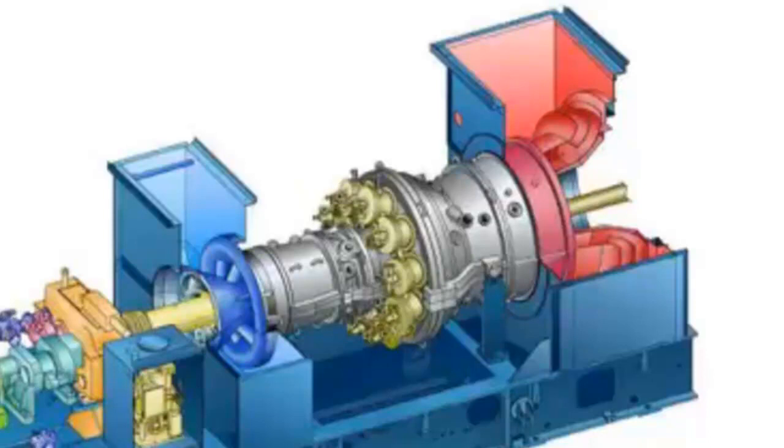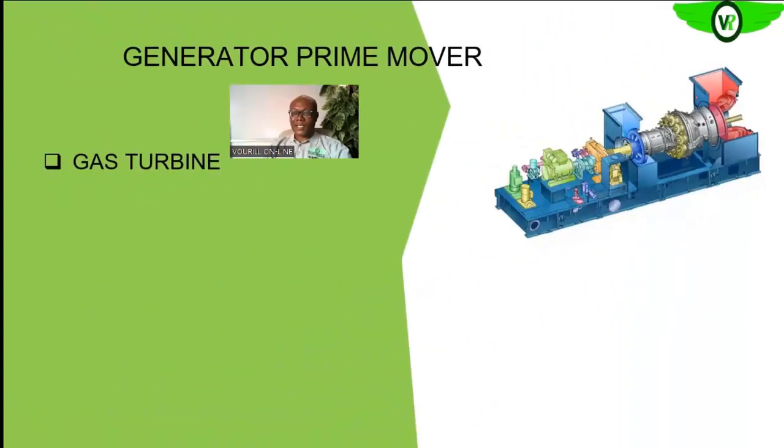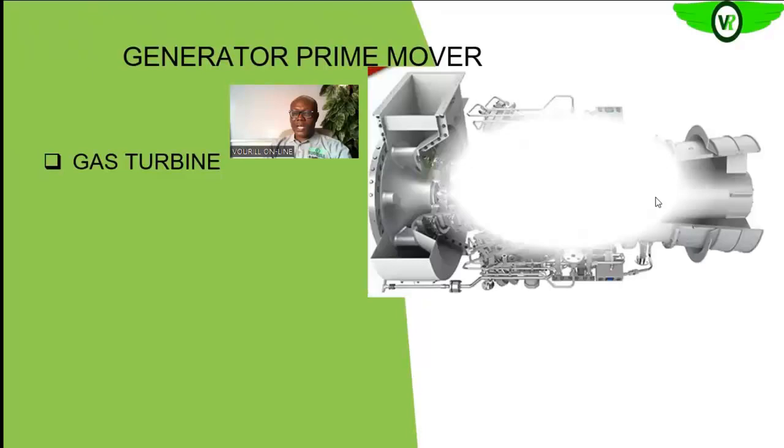The ignition product, which will have a very high kinetic energy, is sent into the turbine section by the transition piece. As it goes into the turbine section, blades in the turbine extract the kinetic energy contained in this high energy combustion product and convert it into rotating mechanical energy. We'll see how it does so later.